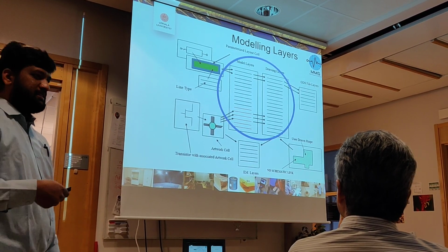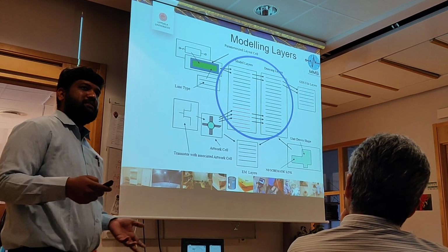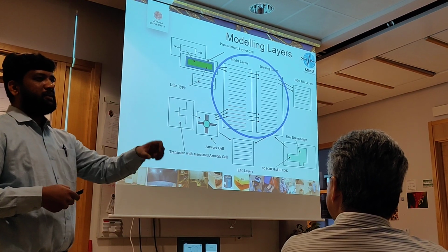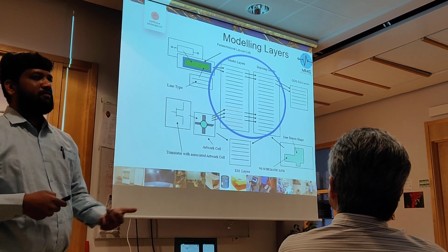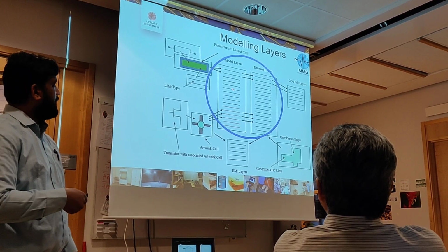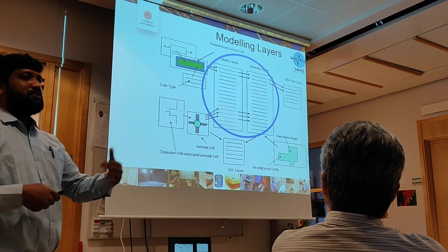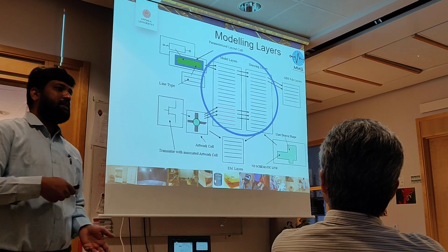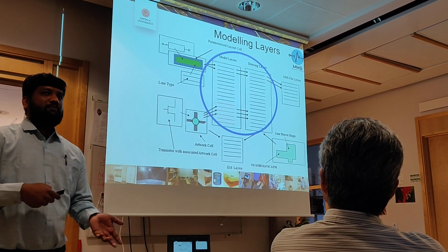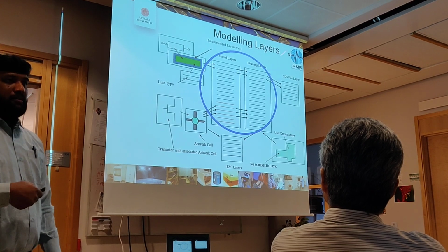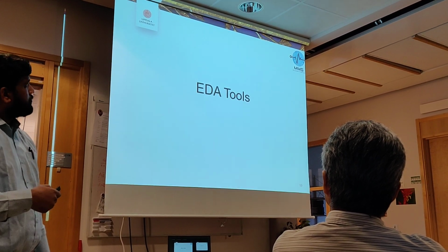Sometimes there are bad practices, like downloading some models from the internet and directly putting them in your design, and if you do not have the proper linkage between model layers and drawing layers, then the analysis will be wrong. Even though the circuit looks better in your schematic and layout, once you fabricate it, you will not end up with a proper testing prototype.